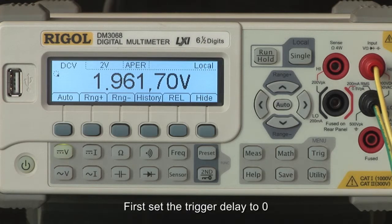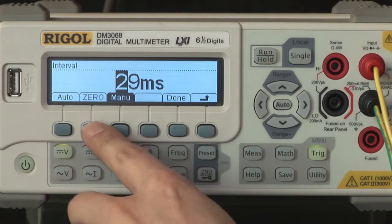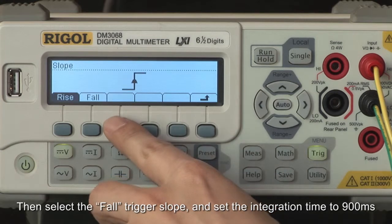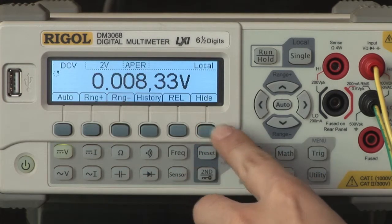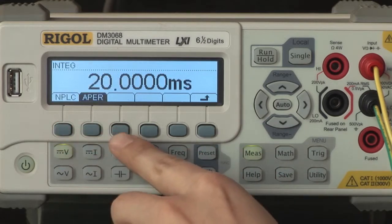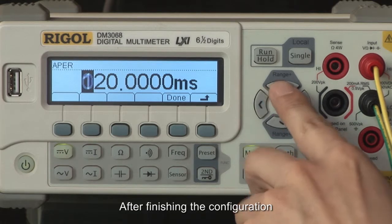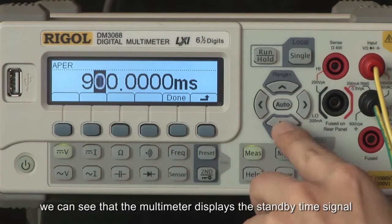First, set the trigger delay to 0. Then select the fall trigger slope and set the integration time to 900 milliseconds. After finishing the configuration, we can see that the multimeter displays the standby time signal.